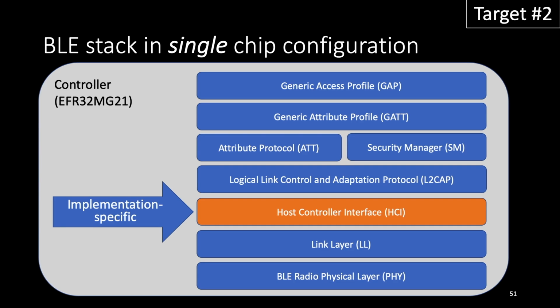And this Silicon Labs chip is one of these single-chip configuration cases. So all these protocols reside on the controller device. So when I show you the demo, you will not see any interaction between the host and the controller through this HCI interface.